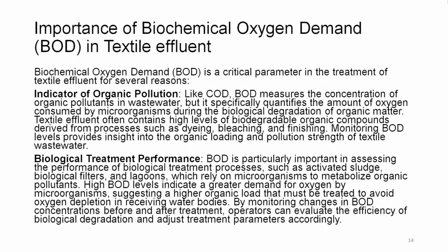Biological oxygen demand, BOD, is a critical parameter in the treatment of textile effluent for several reasons. Indicator of organic pollutant: like COD, BOD measures the concentration of organic pollutants in the wastewater, but it specifically quantifies the amount of oxygen consumed by the microorganisms during the biological degradation of organic matter.